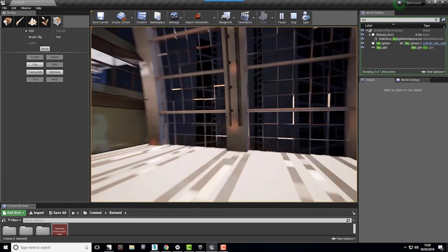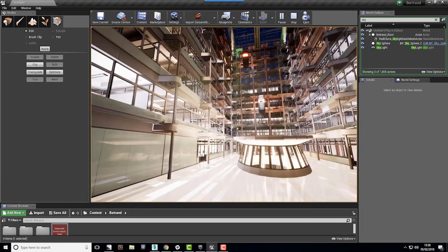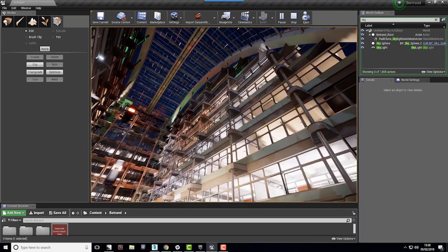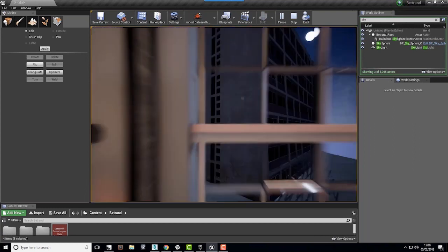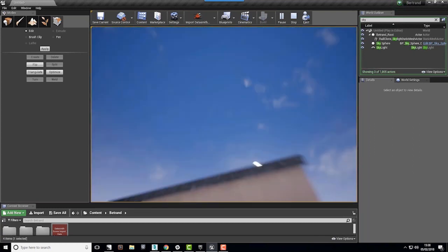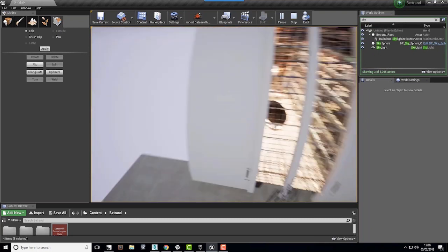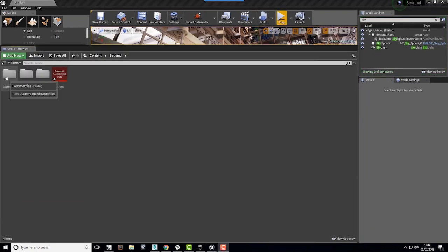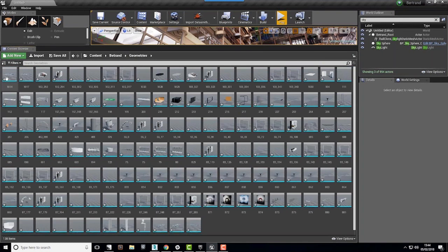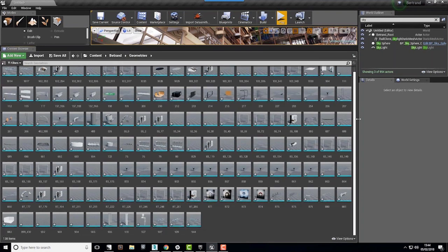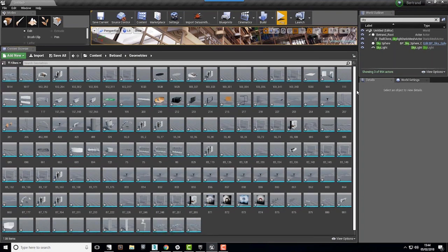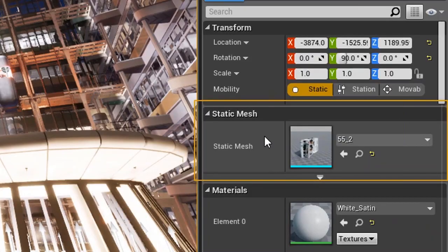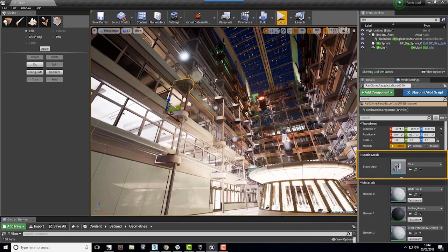So this was made of a lot of individual rooms, basically, chunks of facade and that kind of thing, all of which were instanced in 3ds Max for efficiency. In Unreal, those are also still instances, which is handy too, because it means if you need to change them all, you only need to change one. And here we can see all the instance bits and pieces. So that's a really nifty feature of Datasmith, that it supports both of our plugins.